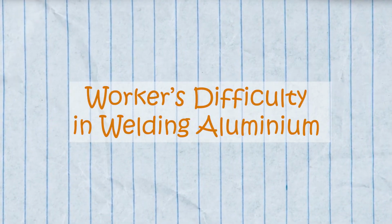Therefore, if you were to bolt it, I think it's a more controlled assembly process, making it a more effective process in general. The second reason would be difficulty in welding. Now, since aluminum has a comparatively lower melting point in comparison to that of steel, it tends to form an oxide layer on top, making it difficult to weld. I think it's aluminum oxide that's formed on top. That makes it an added level of difficulty in the entire welding process. That'd be your answer.